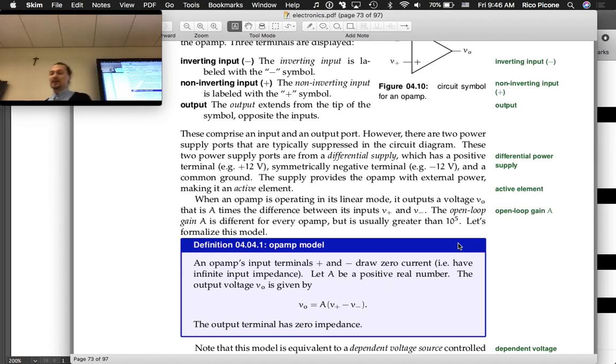Another situation where distortion is a problem is in measurement systems. This is related to 315 as well. If you're measuring things, you want fidelity to the original signal. But if the original signal is small, you have to amplify it, and if you distort it, you don't have a very good measurement of your original signal. So linear amplification is very important.